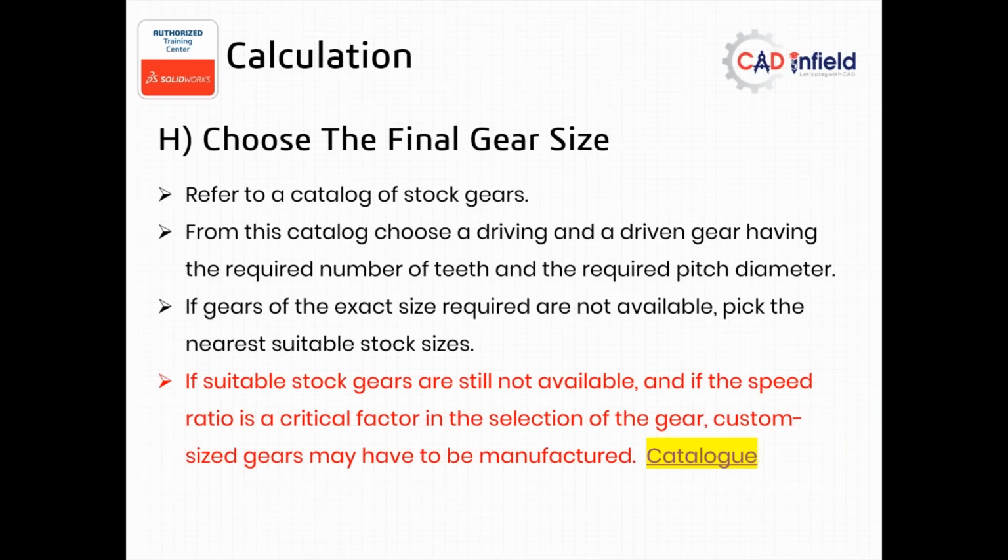We need to pick the available gear, and once you select it, you have to check with the manufacturer what kind of stress and strength, or what different ratios are associated with that specific gear, so that it can be used for your application and there is no failure from stress or deformation. So that's the way the first selection will happen.